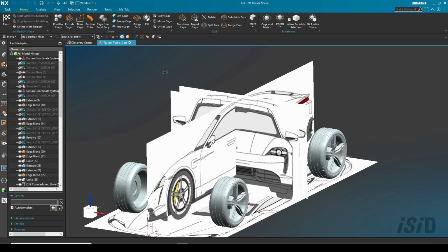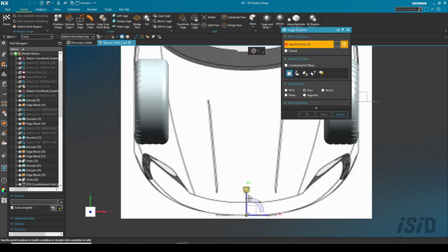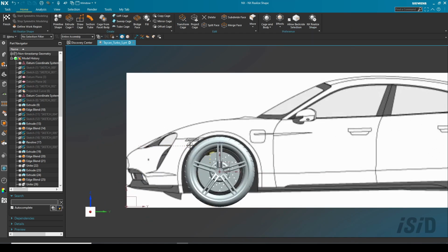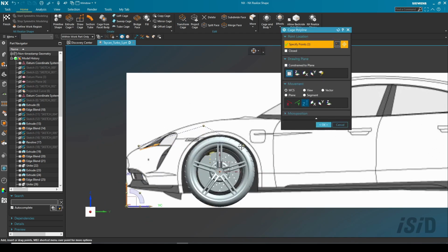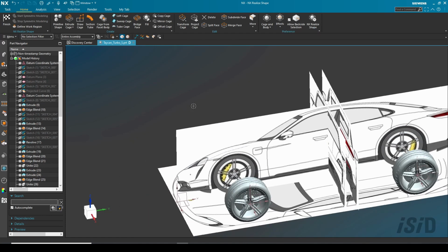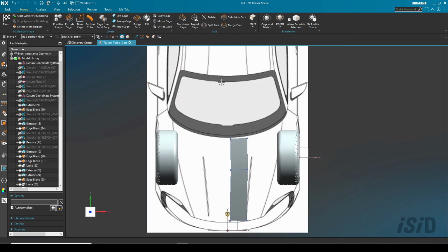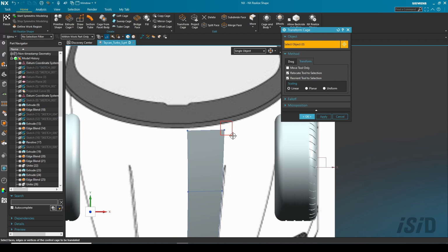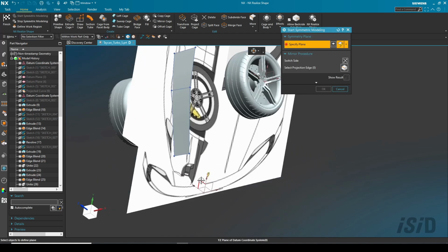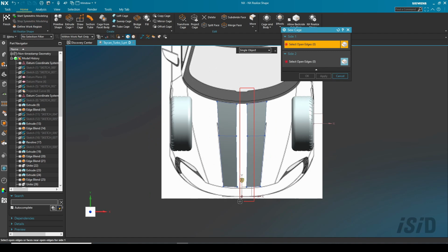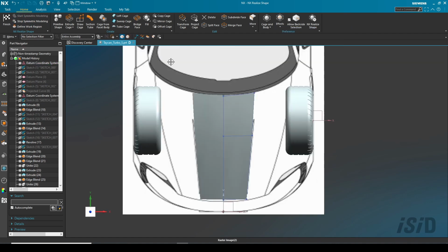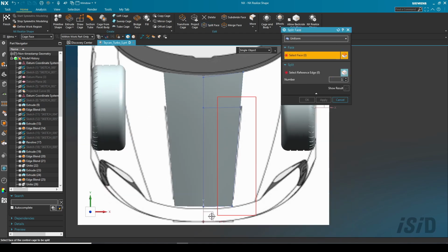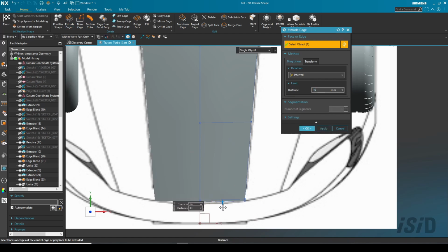To begin with, I need to activate the NX reality shape and start building the hood surface. Firstly I need to create some curve. The curve that I use is a cage polyline. This tool is for creating a curve, but for subdivision modeling. And then I add more refining shape by turning on the symmetric modeling and adjusting more vertices or cage edge using transform cage command.